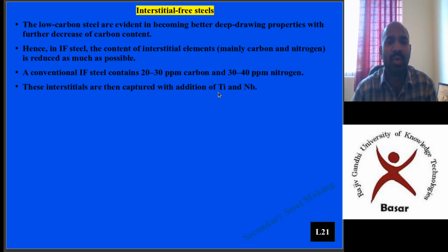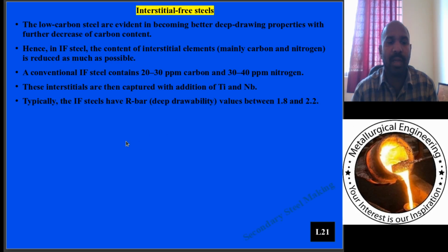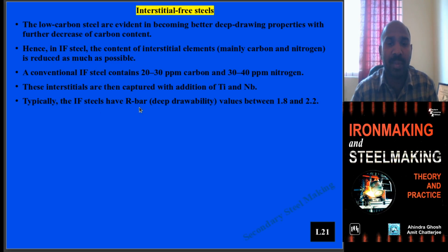That is done by this addition of elements. These interstitial free steels have the R bar, a parameter which gives an idea about the deep drawability of steels.